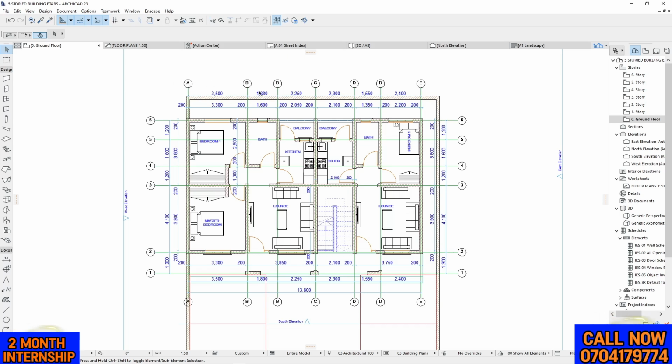Now, remember that the architect is not going to place the beams and the columns for you, so you're going to need to do what we call the beam column orientation. But of course, you're going to have the grid lines. The architect might provide you the grid lines, but you can go ahead and customize them so that they fit the design that you want to do. You know what I mean?